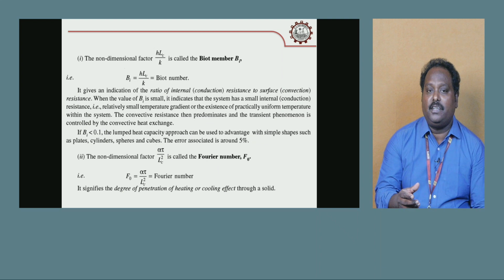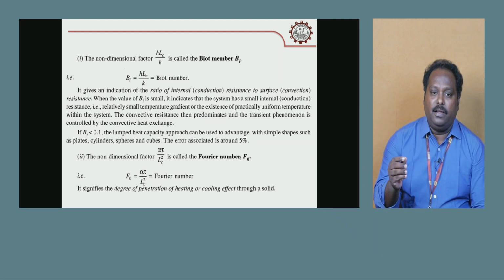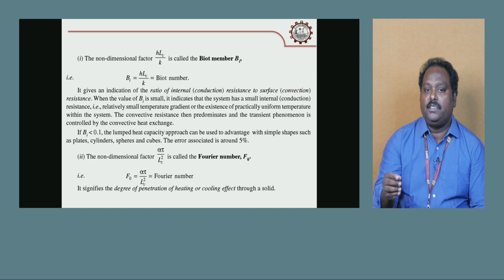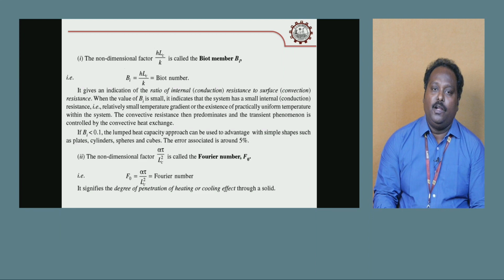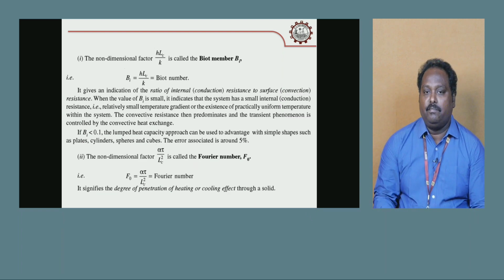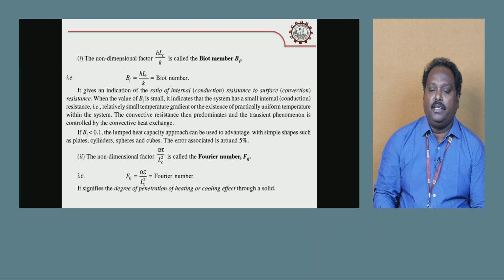In steady state heat conduction, heat transfer does not vary with respect to time, but in unsteady state heat conduction it can vary with respect to time as well as location. And we have seen applications of lumped unsteady state heat conduction, like cooling of IC engines, pasteurization of milk, freezing of foods, like that.